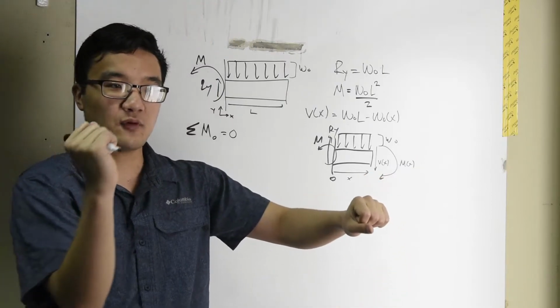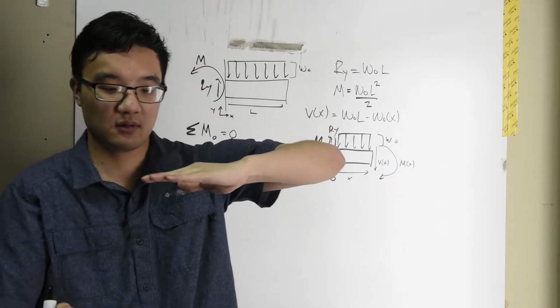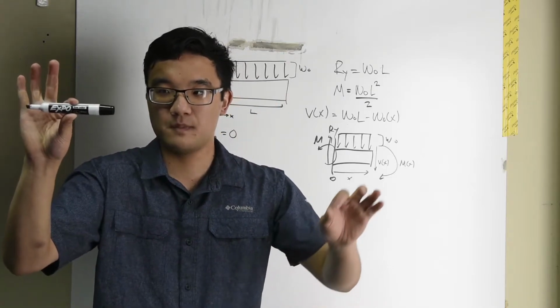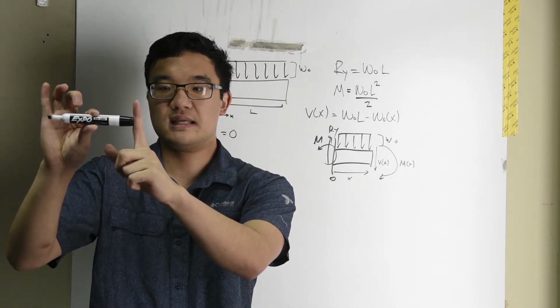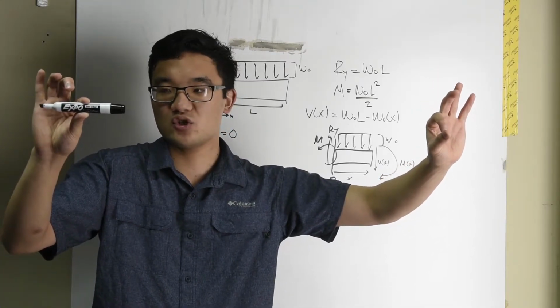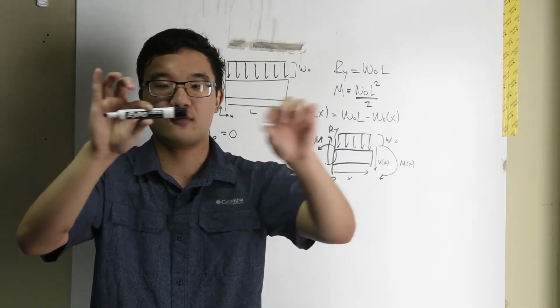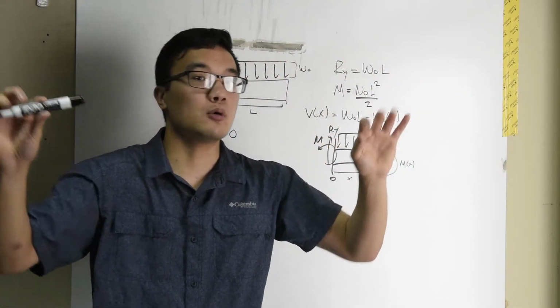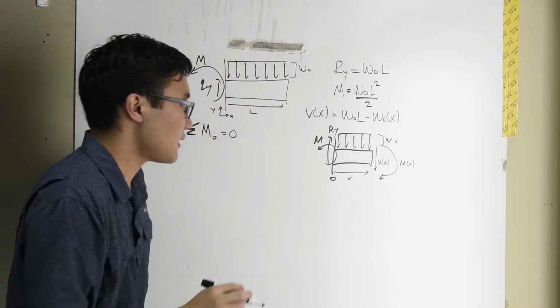But if the force is acting in this direction, and the force arrow is drawn over here and my point's here, there is no perpendicular distance. This force is basically acting through that point. It's just been drawn over here. There's no moment. Very important to remember that.